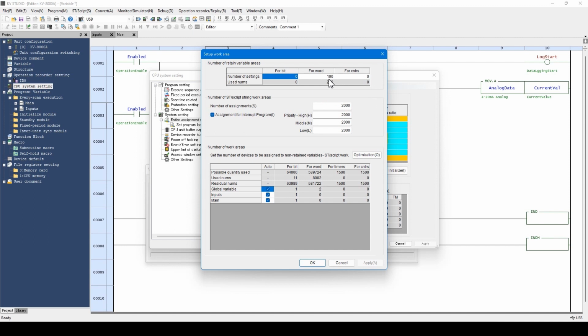When the retain setting is changed, the PLC needs to be changed to program mode before transferring the program. In order to avoid the setting change as much as possible, it is recommended to set the largest value possible when compared to the size displayed here.